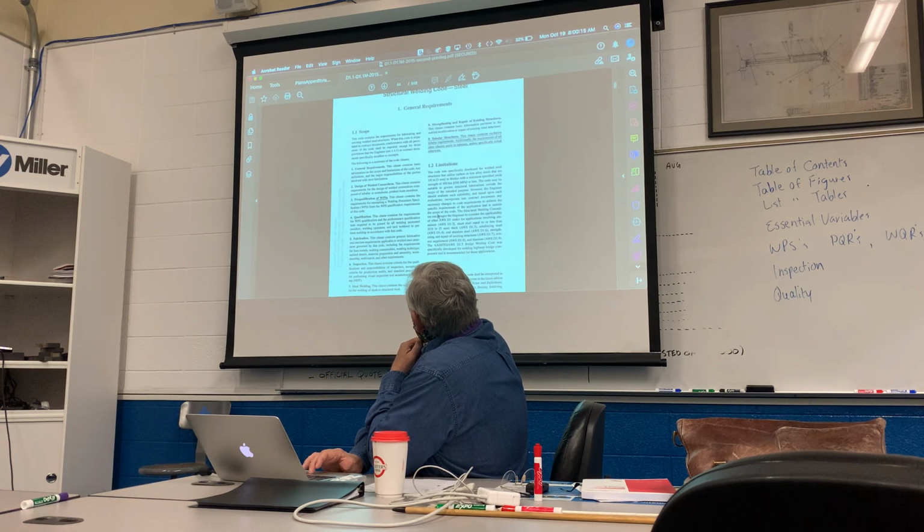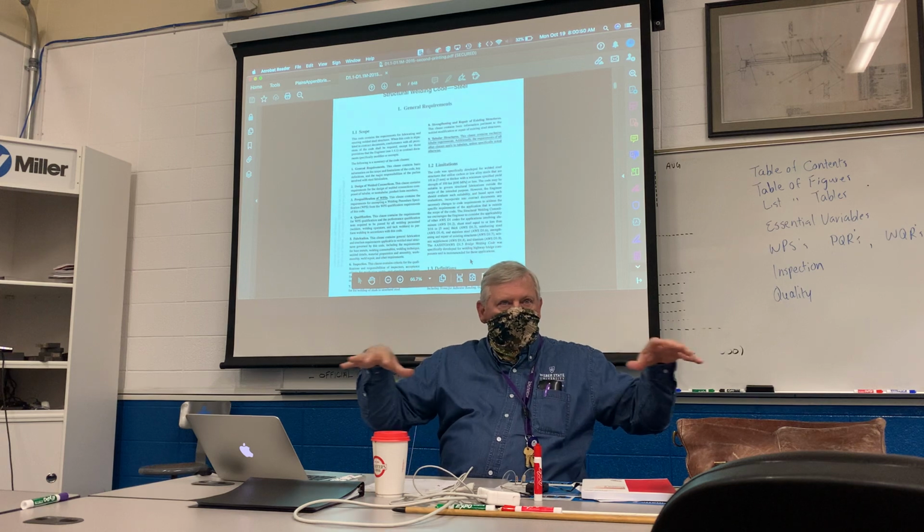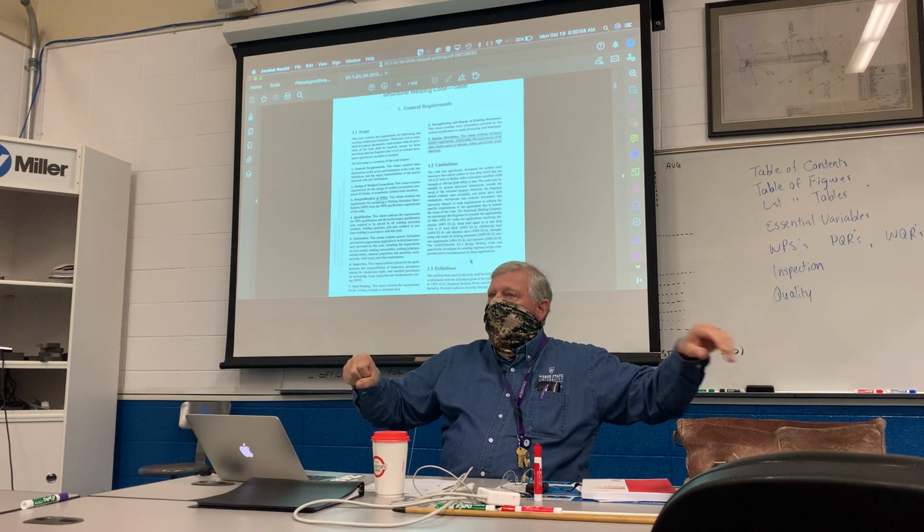So, the Structural Welding Committee encourages the engineer to consider the applicability of other D1 codes for application including aluminum. And here's what I was showing you: D1.2, aluminum; D1.3, sheet metal; D1.4, reinforcing steel; D1.6, stainless steel; D1.7, strengthening and repair of existing structures; D1.8, seismic supplement; D1.9, titanium; and then the AASHTO/AWS D1.5 bridge welding code, specifically designed for welding highway bridge components and recommended for these applications. So there's a breakdown of the D1 code into these smaller subunits. I want you to know that. Titanium's a separate one, aluminum's a separate one.